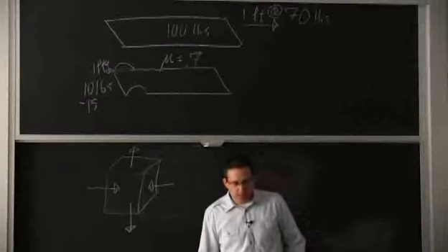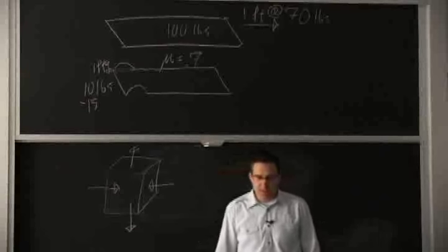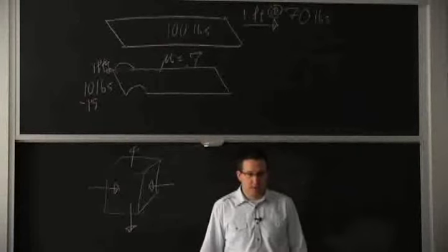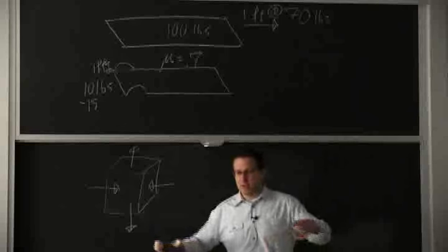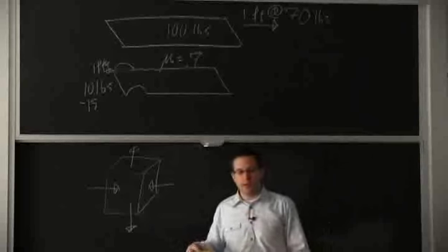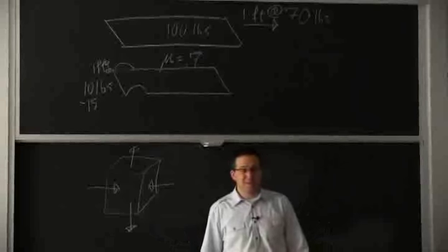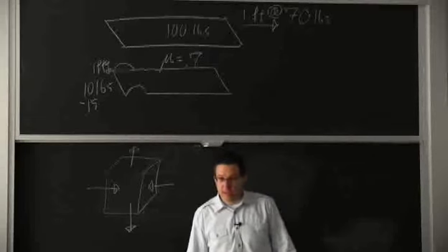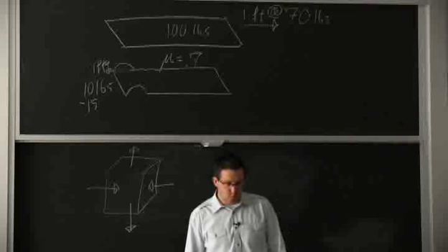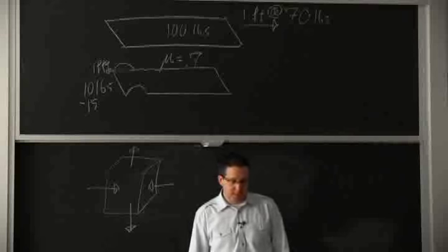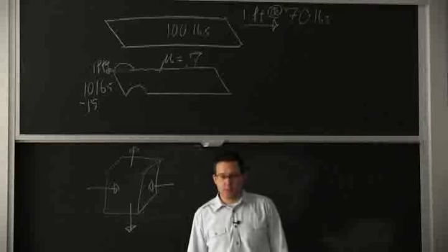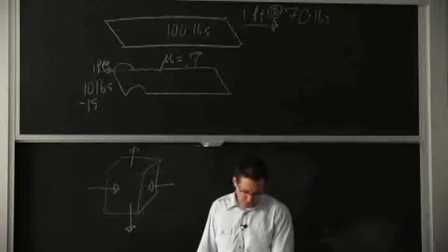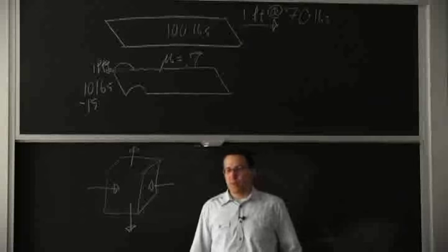And then I say it's only for very ductile materials because the criteria allows you to put as much hydrostatic tension in 3 dimensions that you want on the material, but in reality, eventually, it will break, it will create voids, microvoids, and eventually fracture. It's just not something that the equation includes, but we take it into account separately.